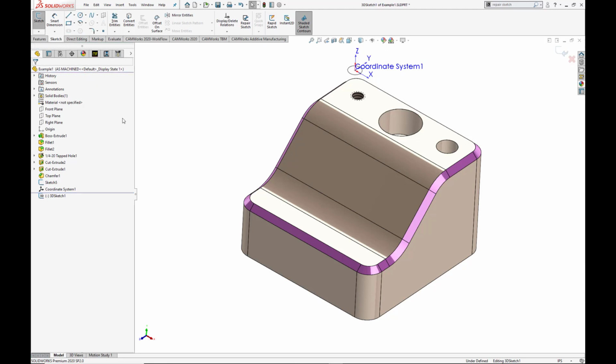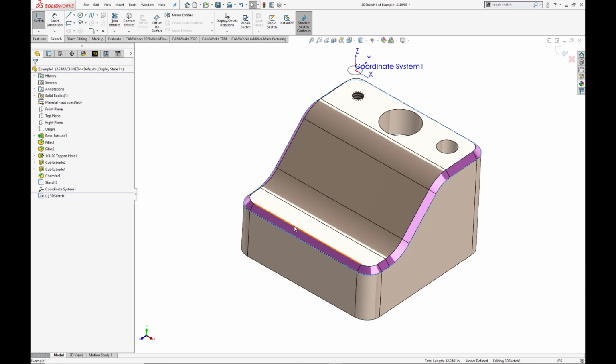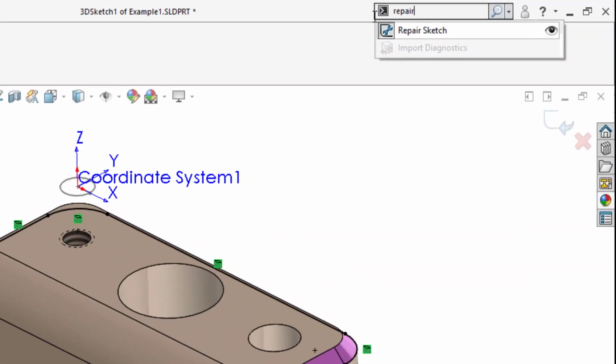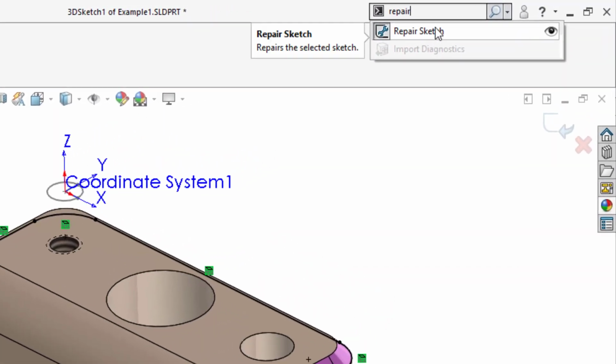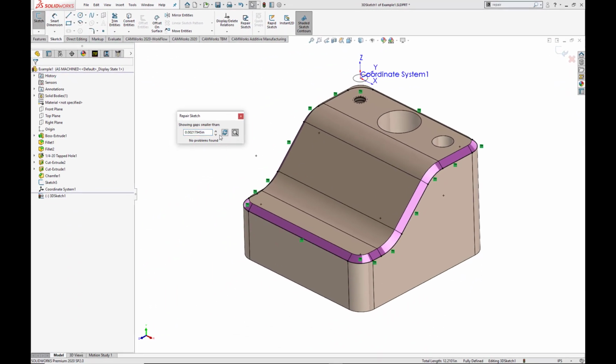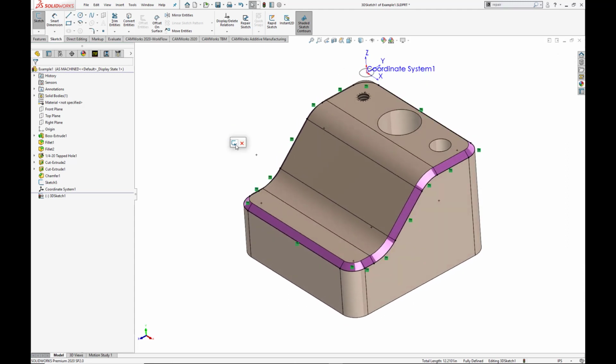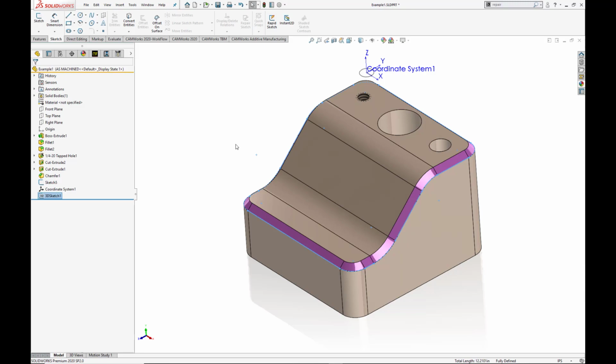With an active 3D sketch open, simply right mouse click on a given edge, select tangency, then utilize my sketch tools to convert entities. Now, since I don't want to be bothered by broken or overlapping sketch geometry, a few mouse clicks of running Sketch Repair with its default settings will highlight and/or address this. This time-saving technique is really helpful when used on imported CAD models such as Parasolids, STEP, and IGES formats.